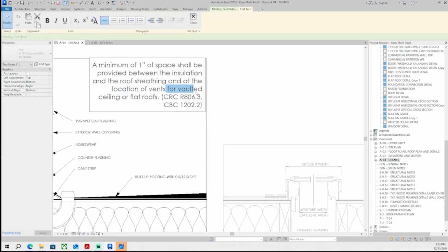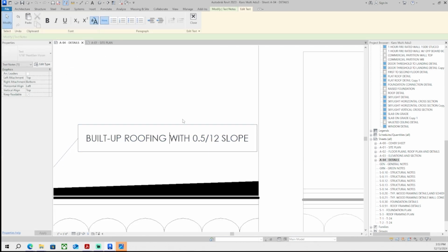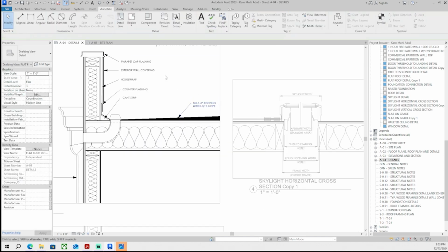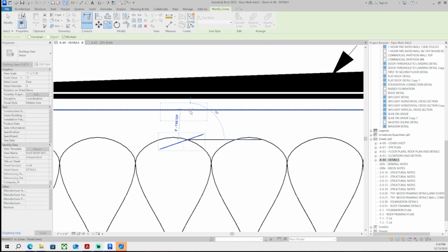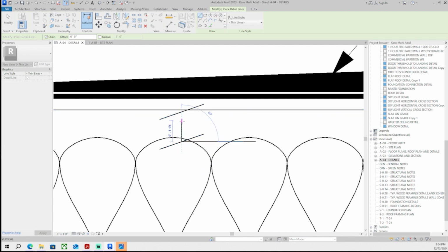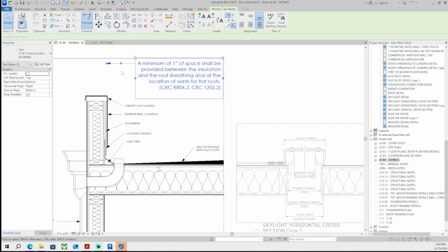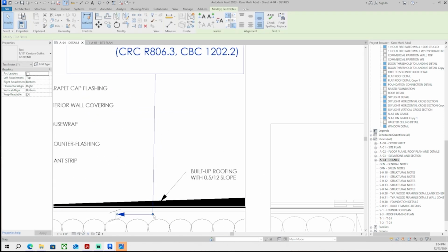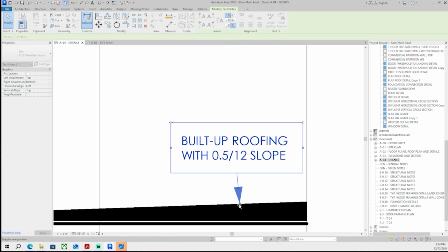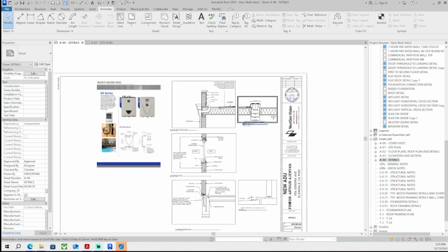Site plan. Okay, going through here, fine. There's a note. Oh yeah, a lot of jurisdictions are asking for a 1-inch minimum gap above the insulation, between insulation and roof sheeting on the roof. And that's if it's batt insulation. I believe if you do polyurethane spray foam insulation, that requirement is lifted. In fact, when you do the polyurethane spray foam, you can't have any gap. You need your insulation to fill up the whole cavity. So spray foam versus batt insulation, there are a lot of different requirements. The spray foam is more expensive,